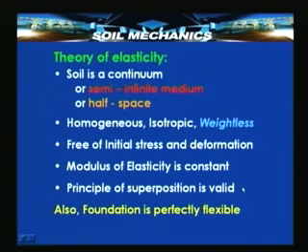That means, if by chance there are two loads applied over the soil, the stress due to the first load and the stress due to the second load can both be added in order to get the total stress due to both the loads. This we had in fact discussed indirectly a while ago. For example, if we want to know the total stress which comprises the stress due to the externally applied load and the stress due to the self weight, then we assume that the two can be superimposed in order to get the total stress.